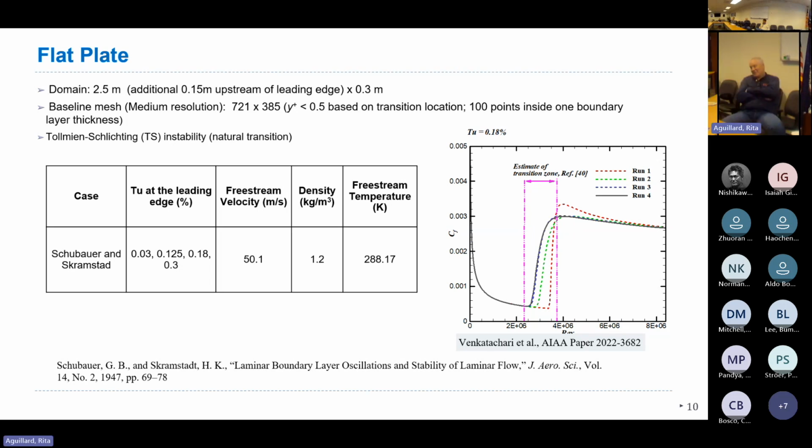Do you foresee wall function based methods for this, partly subsonic, transonic? I think there are some efforts on that. People have tied it with, say, DES. Again, it brings its own set of problems. The DES shielding interferes with the shielding already inherent in these transition models. And then for wall functions, yes, you can use that, but you still have to get the vorticity maximum for some of these. So what Y plus you allow for the wall function is kind of tricky. Wall functions, wall models, DES, that approach, everything is being looked at.